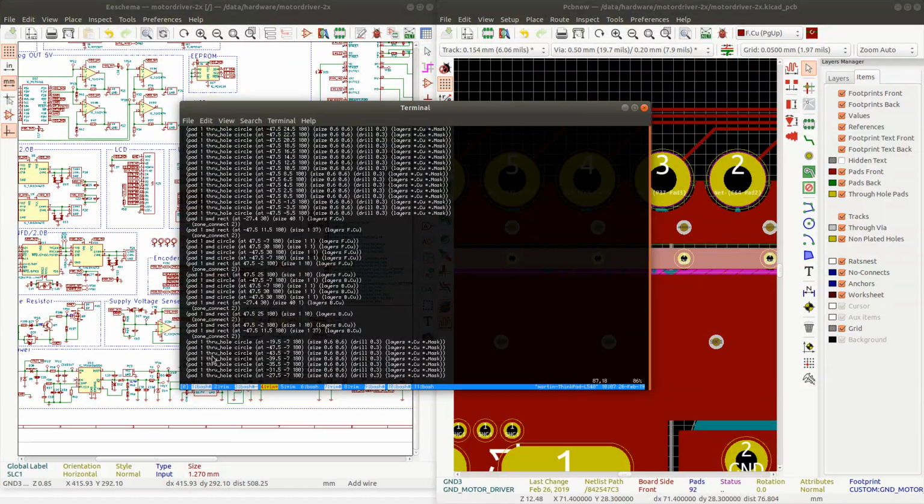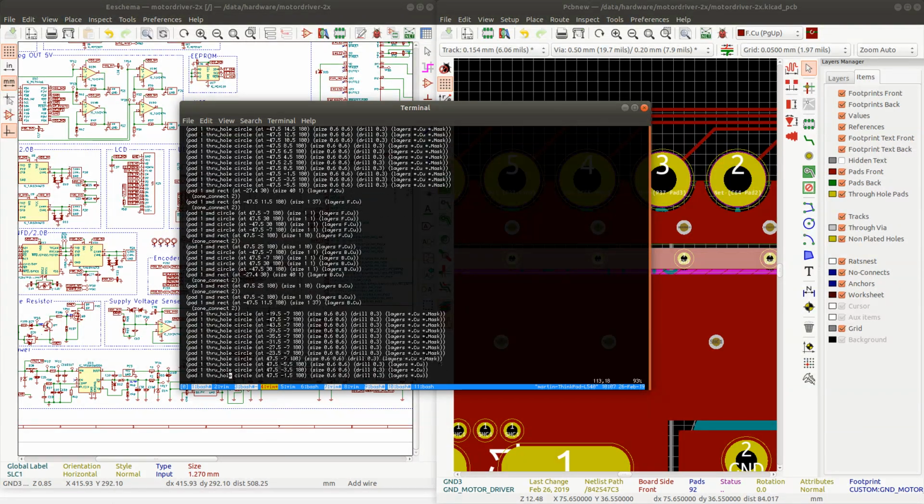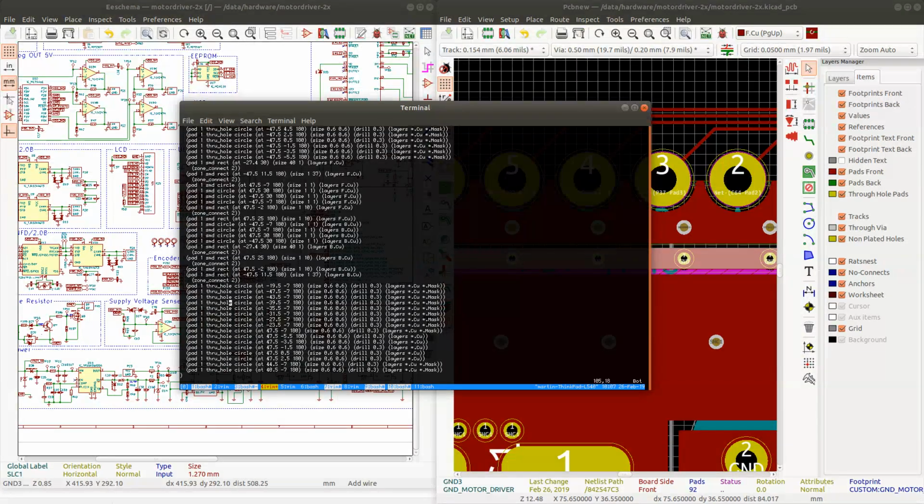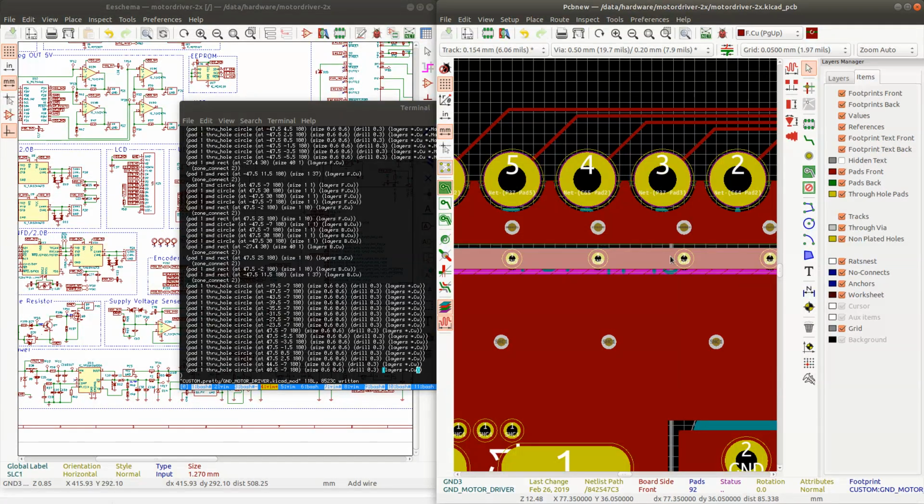And also we have the through-hole pads. The through-hole pads are basically emulating the vias, but they shouldn't have the mask layer, because if they're on the mask layer, they're going to be just naked copper. I don't want that. So I want to remove the mask here, and we can do it like this, delete the parentheses, and then just delete all of them, and that one, and that one, and that's easy enough. Much faster than having to do this manually.